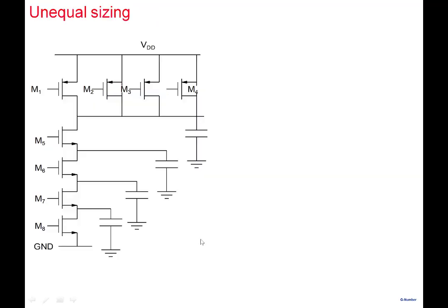All right. This particular issue we had raised earlier. We've been saying that when we take a transistor, we size all of them the same, maybe 8 lambda by 2 lambda. But that's for simplicity. If you wish, you can change the sizes; the size of this one and the size of this one could be different. And one of the thinking is, what would be the benefit that would come from unequal sizing?